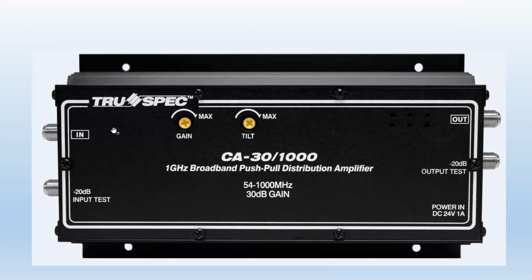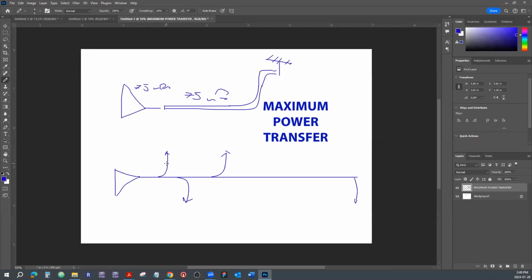So you adjust the gain, and you adjust the tilt, and you adjust the gain, and you adjust the tilt. Sometimes it takes a few times to find the correct balance between these two, so you can have pretty much even signal distribution through the whole transmission line, right? If that's, for example, a school and the CCTV going on there.